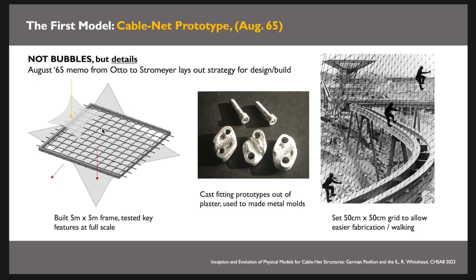So Strohmeyer built this thing out of a series of strips, put it in a frame. Then in the frame, they'd be able to test out how they'd be able to tension it, how they'd be able to hang something from below or even hang something from above. The main takeaway from this idea is that the very first model, no other models could actually happen unless they knew these were possible. You have to establish the cable net dimension first, and you have to be able to see whether this type of system also allows you to pull and tune and tweak it.